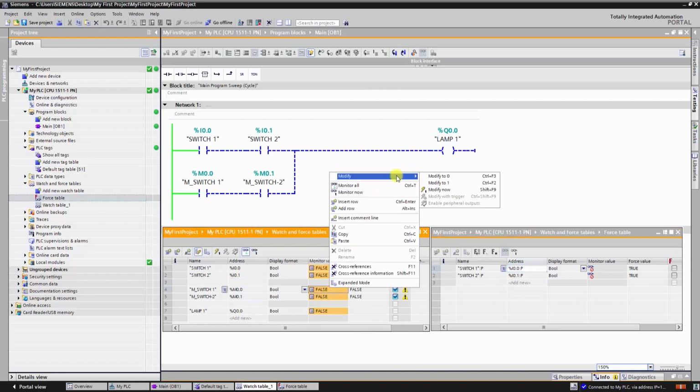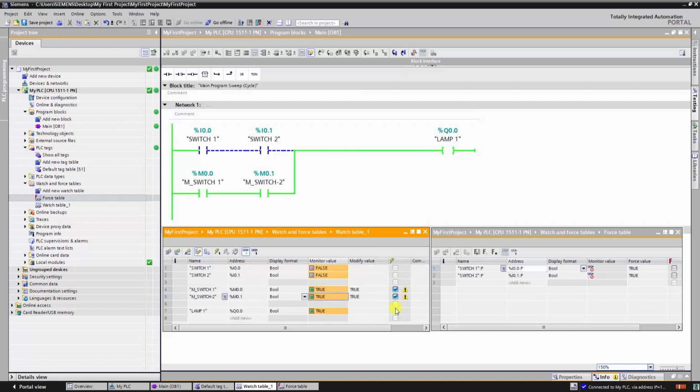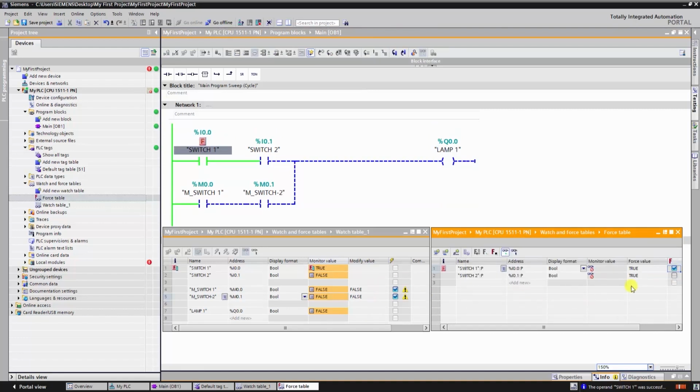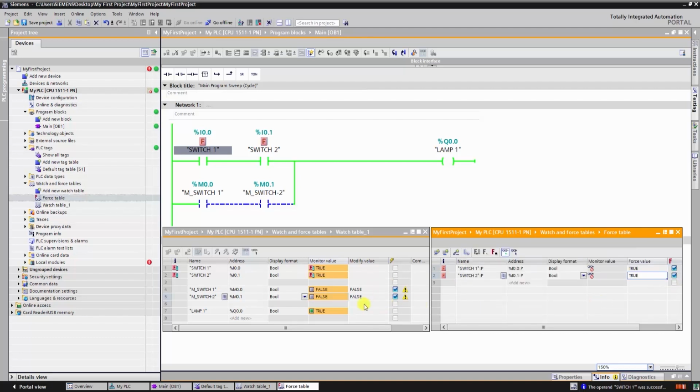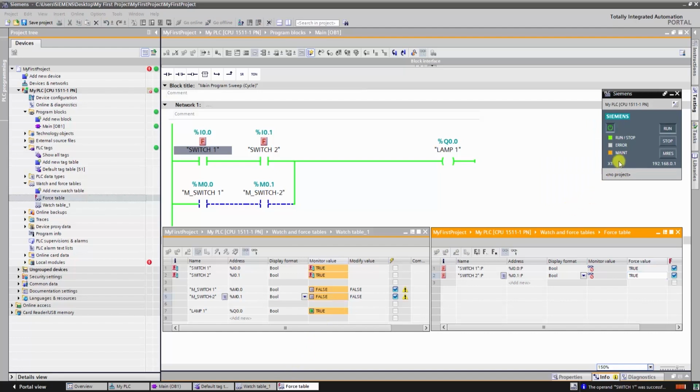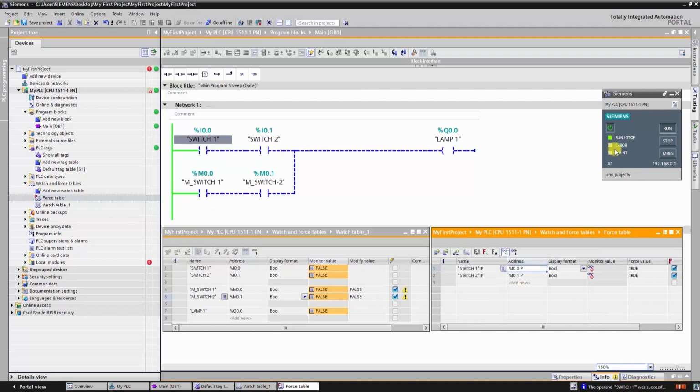Until now, we have learned how to create a new project in TIA Portal, how to add a controller and then configure its port. Then, we have learned how to create a program and how to test it via a real controller, or via PLC Sim. There is an important thing we should learn before going to the next lesson: how to address tags in TIA Portal. To understand what I0.0, I0.1, and then M0.0, M0.1, and finally, Q0.0 mean.